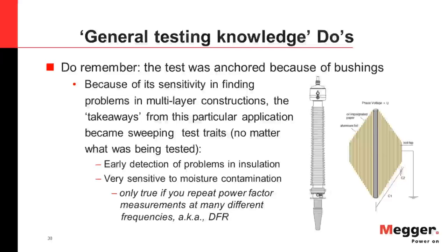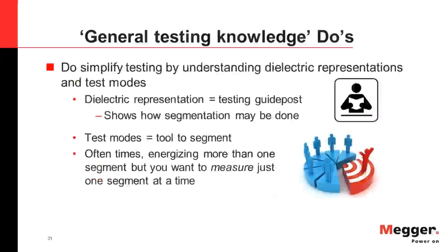The next general testing knowledge to learn is to appreciate dielectric representations and test modes. This knowledge will be empowering, and it will greatly simplify power factor and capacitance testing for you. Throughout this presentation, we will be stressing the importance of minimizing the size of insulation you test. Smaller is better. But how can you chop up an asset's insulation system?